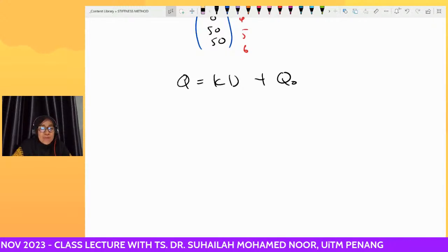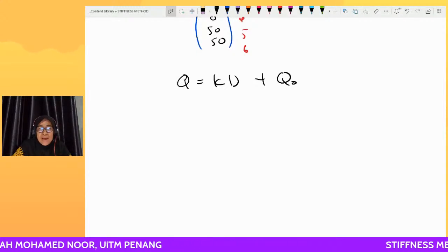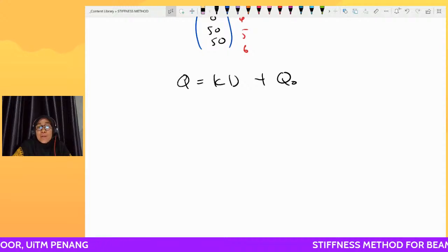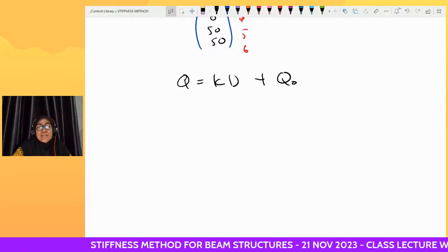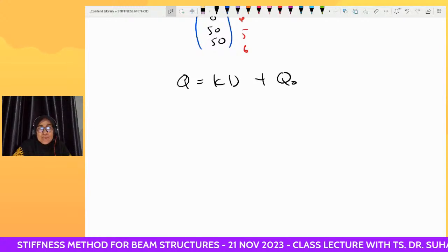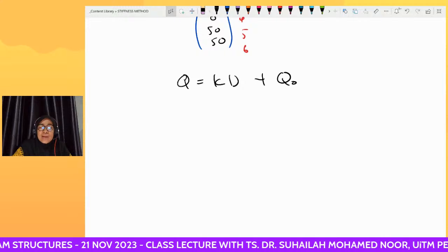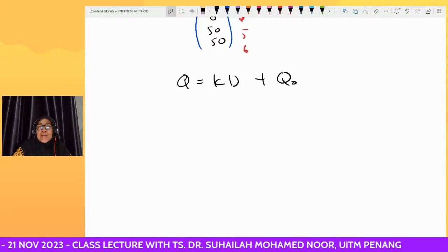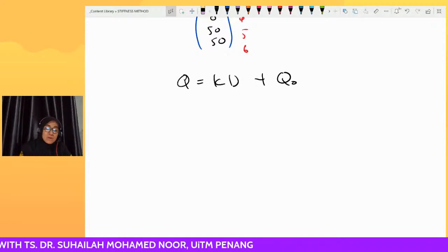You only need the stiffness equation corresponding to the unconstrained degrees of freedom, because we get the unknown displacements by only considering the unconstrained system, and it has only 2 degrees of freedom.